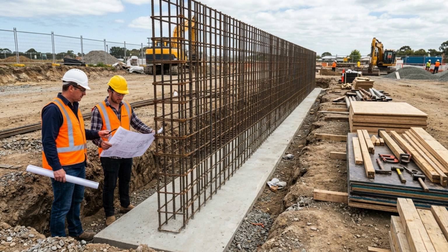A strip foundation is a continuous shallow foundation used mainly for load-bearing walls and closely spaced columns, where isolated pad footings become impractical. It distributes structural loads evenly over a larger area of soil, making it an economical, stable, and efficient foundation system for low-rise buildings with good ground conditions. Although it offers many advantages, including simple construction, excellent load distribution, lower cost, and faster construction, it should only be used where the soil has adequate and uniform bearing capacity.